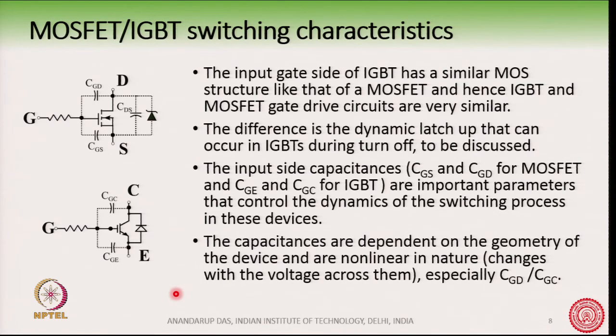So, here you can see that there are capacitances CGD, CGS, CGC, CGE. They originate from the structure or the geometry of the device. And the basic idea of this switching characteristic is that we have to charge or discharge these capacitors.